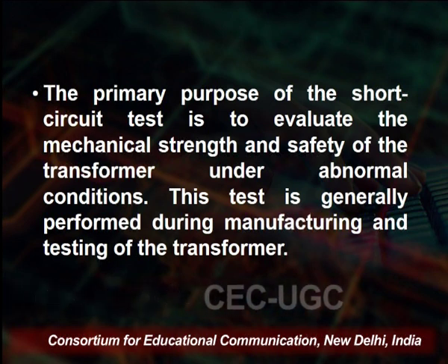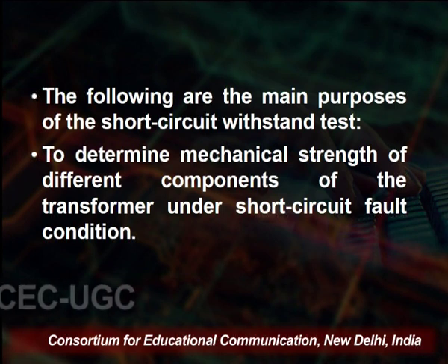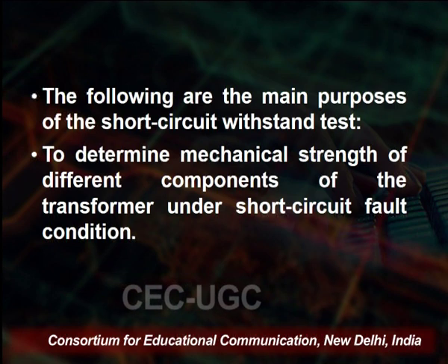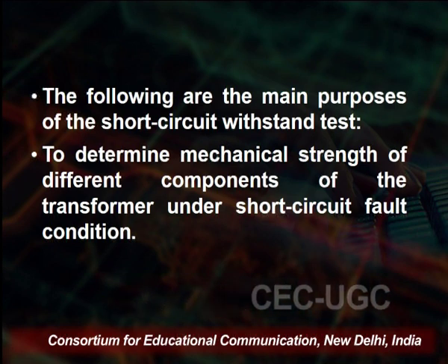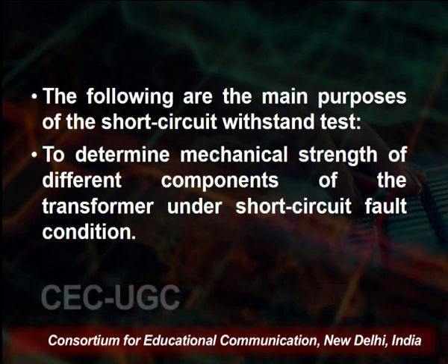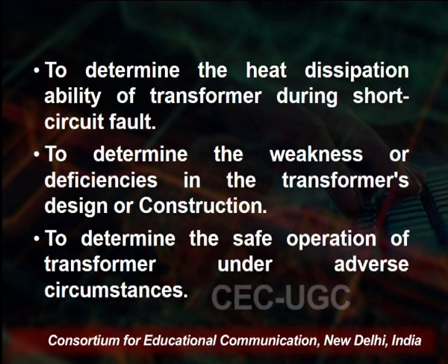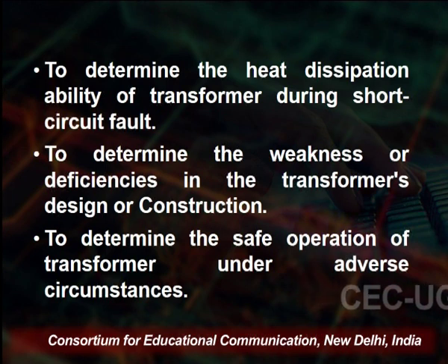This test is generally performed at the time of manufacturing and testing of the transformer. The following are the purposes of the short circuit withstand test. Number 1, to determine the mechanical strength of the different components of the transformer under short circuit fault condition. Then, the heat dissipation ability of the transformer during the short circuit fault can be measured.